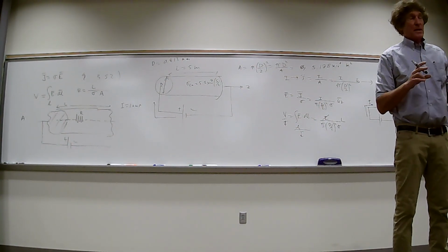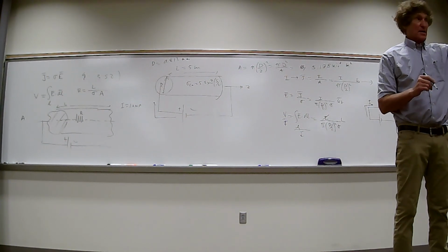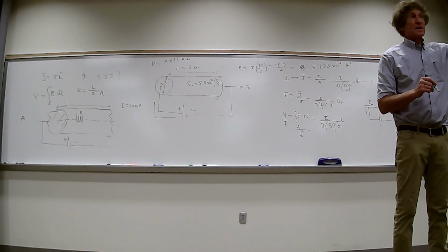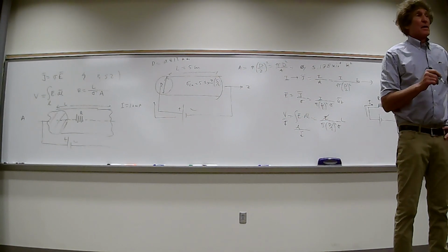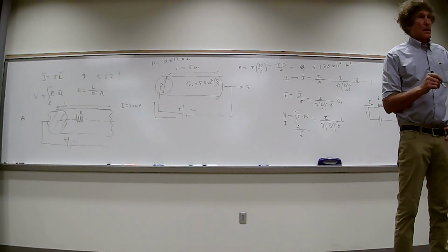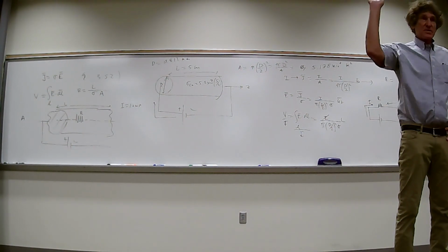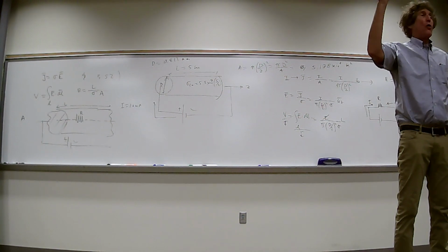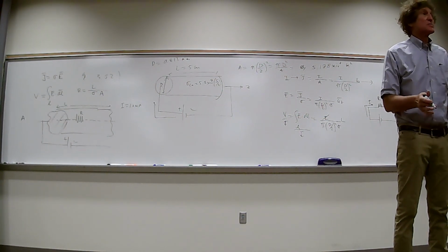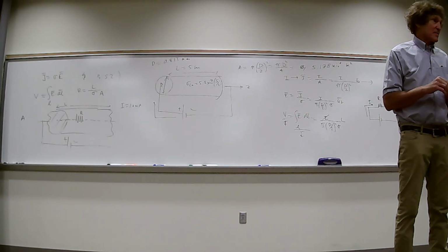All right, but the ones that usually are more tricky, where you have a variable conductivity versus position in spherical or cylindrical coordinates. Did you have another question? I was going to ask, if I was going to try to set up the integral on that, what would my bounds be? Just from 0 to L. It's over the length. That's all it is. There's nothing tricky about this at all. And it's always positive, because the resistance will always be positive. You don't have to worry about getting the sign wrong.